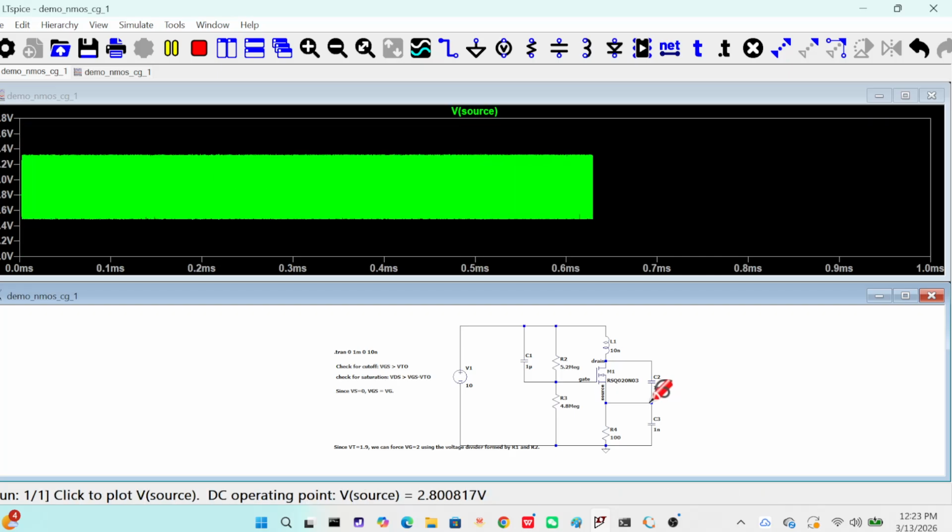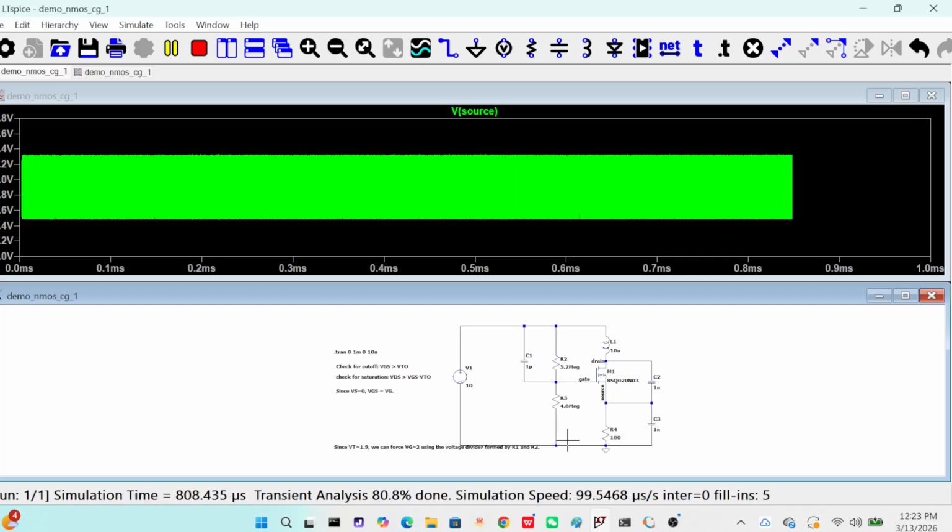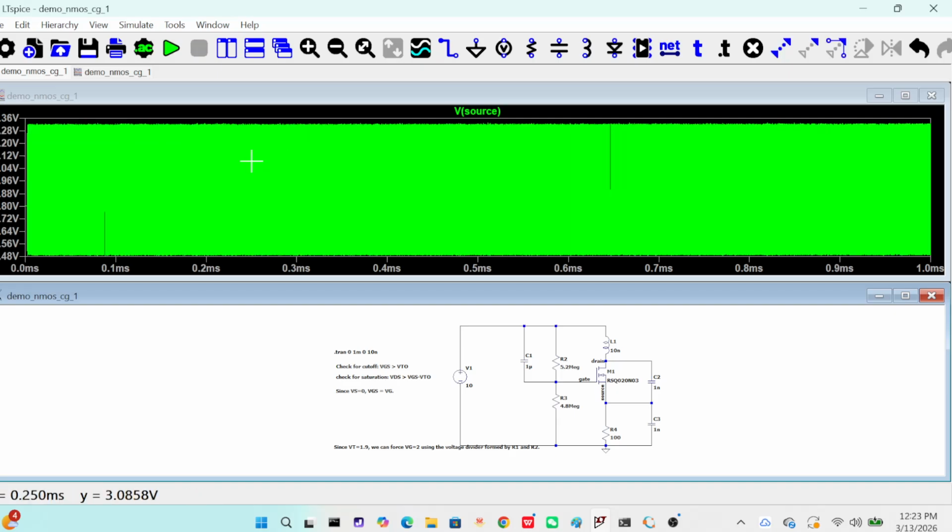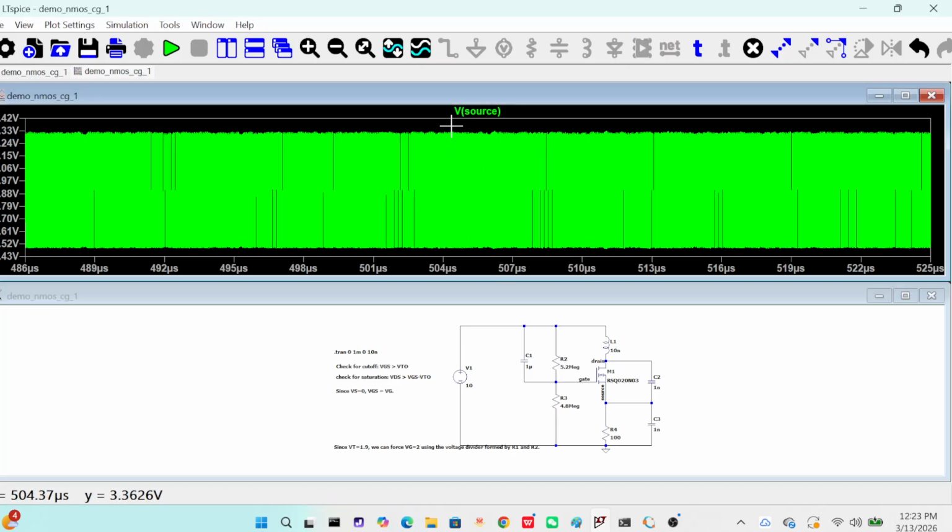So you can see I managed to attain oscillation. But the amplitude here is from 2.5 to around 3.3. So the amplitude is no more than 1 volt. This is an indication that I'm now nearing the upper corner of the frequency. And let's check the frequency.